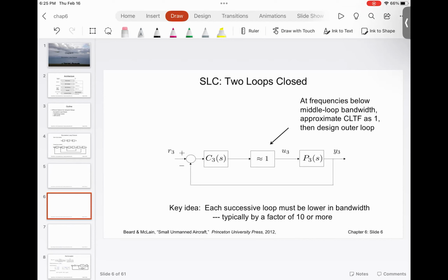Once this whole thing is balanced, you pretty much have all the loops closed, and then you have flight stabilization, or you can use the same technique for path and other controls. So the idea is, once you have a cascaded transfer function that we generated from the lateral and longitudinal dynamics, we successively make all those internal loops equal to one. And this technique in practice works very well.